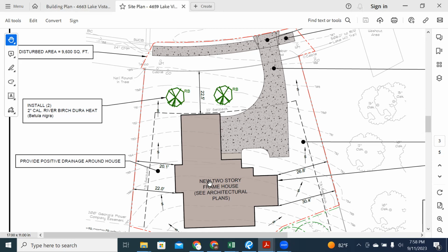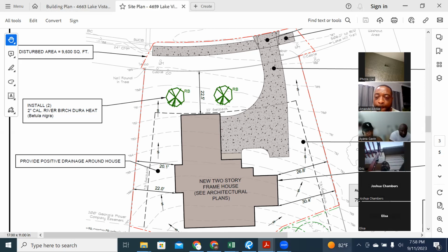Now, there are two kinds of pump trucks, and there's only one that the concrete company cares about: the line pump. When the company asks whether you have a pump truck out there, they need to know if it is a line pump. The line pump is like a small camper almost, a small little unit on wheels, and it has a hopper that they pour concrete into. Then the line pump shoots the concrete out to where it's needed. That line is usually 2 inches or 2.5 inches thick.